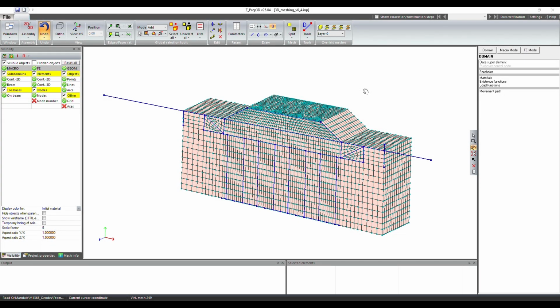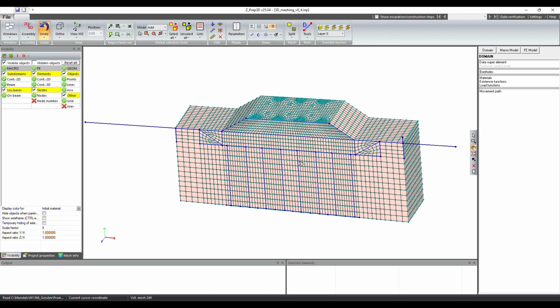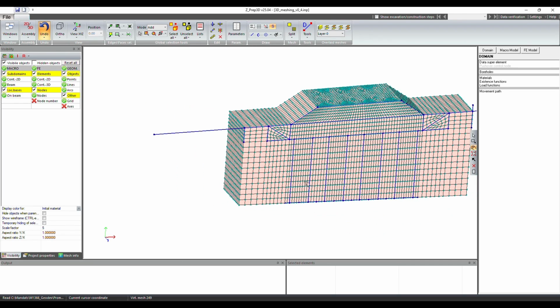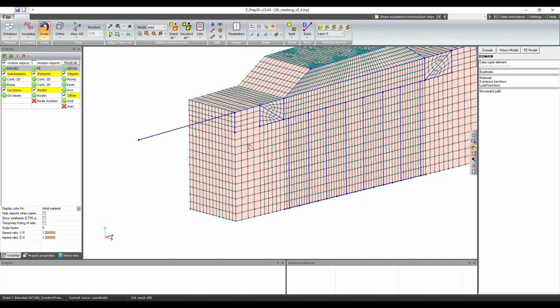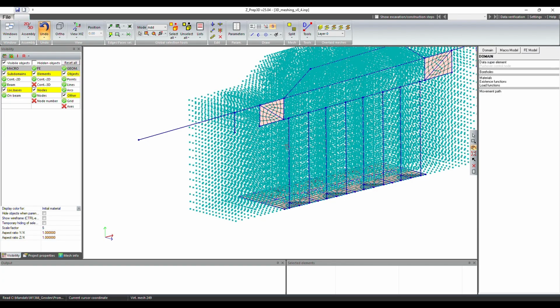The next step in this tutorial is going to be to extend this mesh even further laterally, and while we do this we coarsen it a little bit such that we save memory and computational effort. So we will start doing this on the level that is horizontal here.